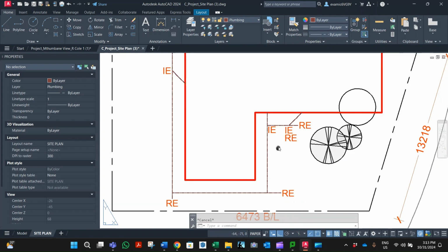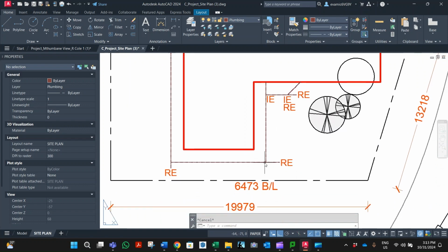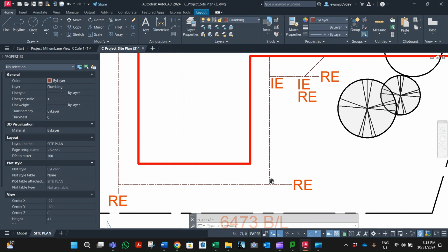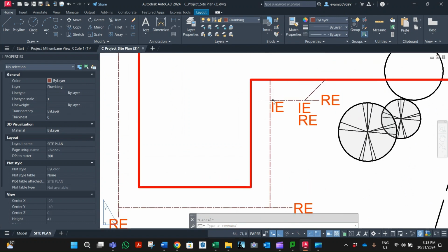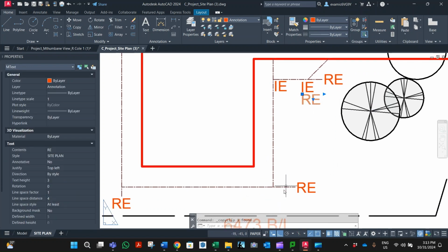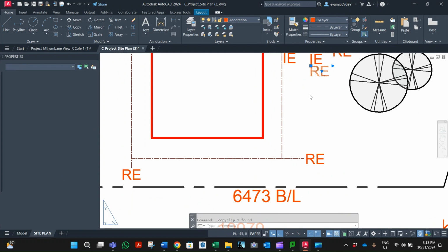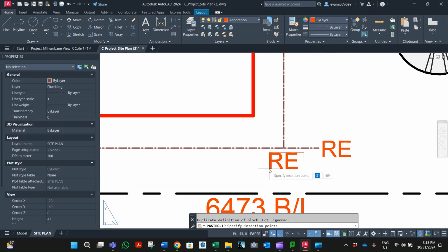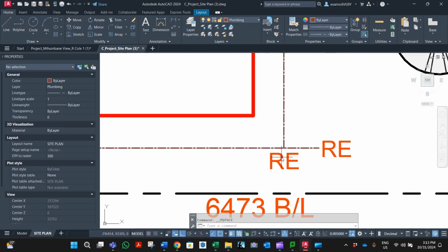What you might want to do here is have an inspection chamber, and I'll tell you why. I suppose I could rod from that inspection eye, but I'm going to add an inspection chamber here because I just feel like we need that additional one on here.